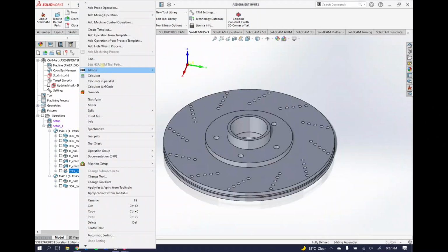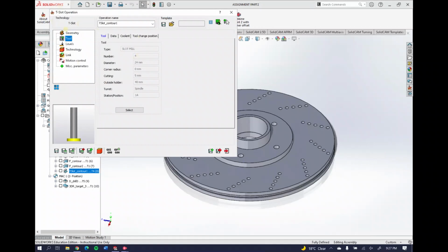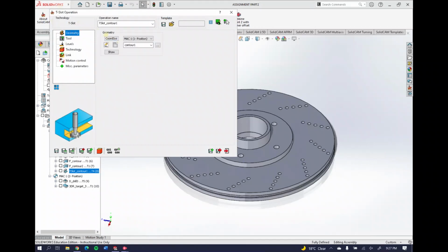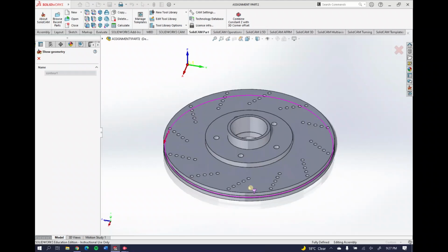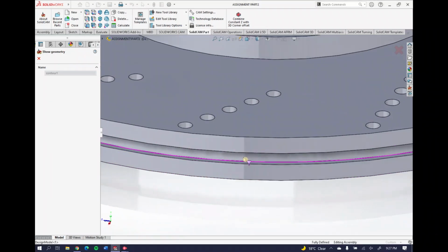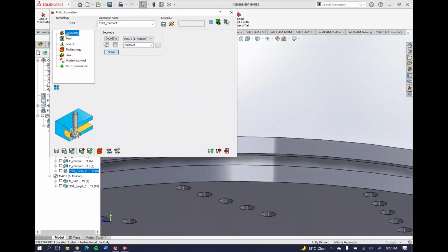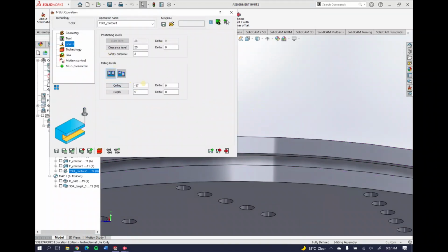And finally, we needed to make the slot on that side, so that's why we had the slot tool in our tool table, the slot mill, sorry. And here is the geometry that we use. So we'll just select here, and the tool being 5mm, it would cut from that side, from that level, sorry, and then the ceiling of it would be this top part here. Here's the level ceiling of -37, which is over here, and the depth of the cut will be 5mm.